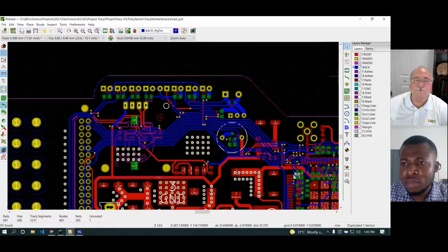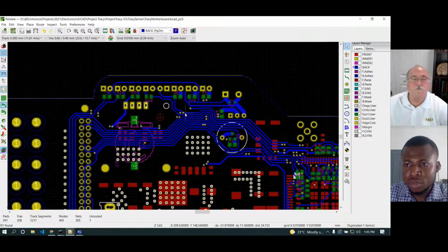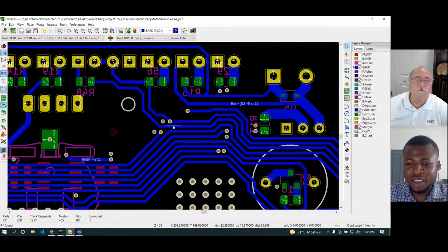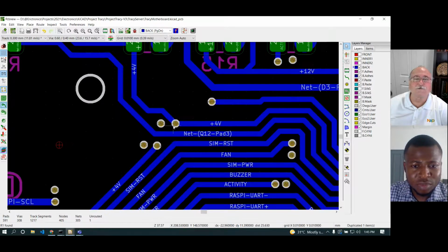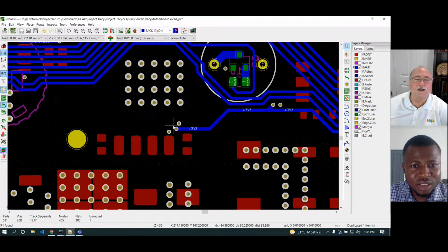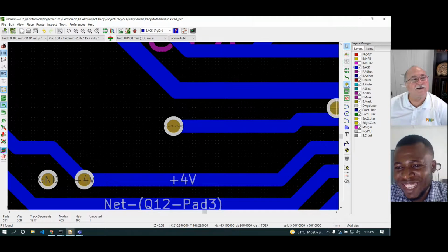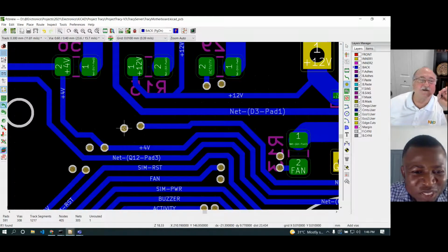So if we look at layer 4, this is layer 4. Every place there's a via by itself, like to the right of your cursor and up. There's one in the middle top of the board. Up where you were just at. Right there. There is an orphan via. This is the fine tuning. So this orphan via needs a friend.